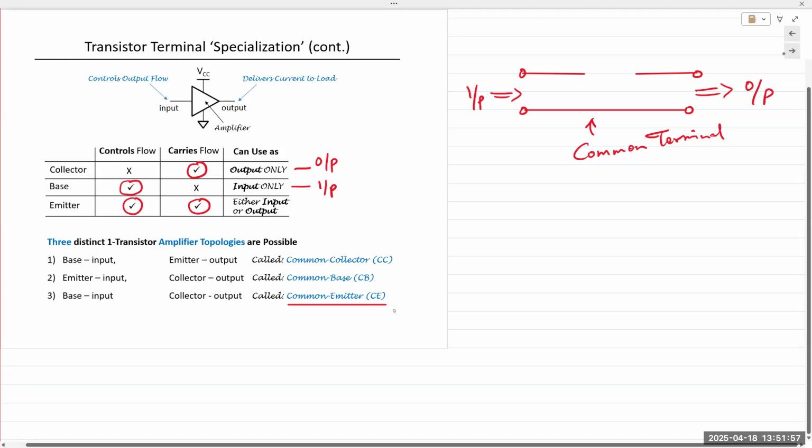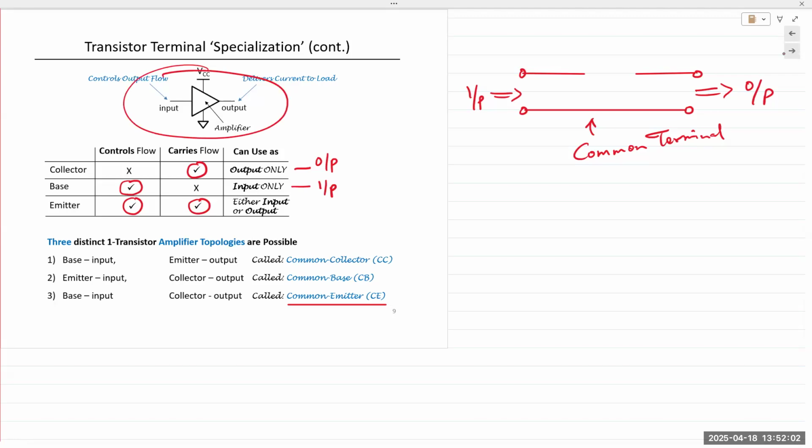So what we are going to do is look at amplifier characteristics, because we want to use the BJT as an amplifier. There are 3 modes of operation for a BJT, or 3 regions of operation: active mode, cutoff, and saturation. We'll look at these again later in this chapter. When we use it in active mode, we can use the BJT as an amplifier, and that's what we are looking at. We are not looking at anything else.